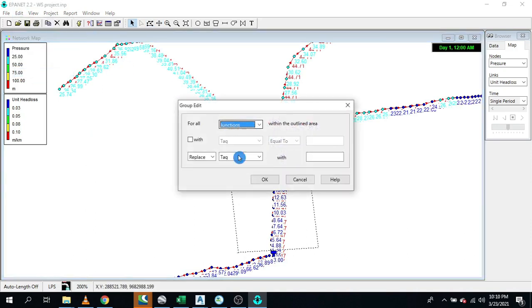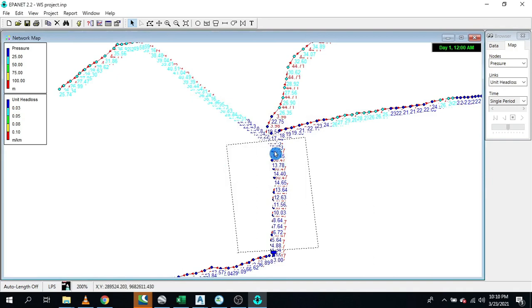Okay, select this region. Let's increase pipe diameter here at least to 75 millimeter pipes with 75 with 49.9, sorry, 69.2. So this is a 2-inch, is 75 millimeter pipe with internal diameter of 69.2. Then select enter, select OK.